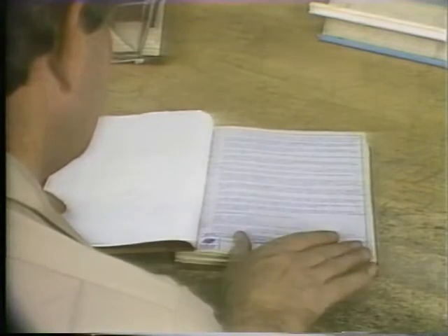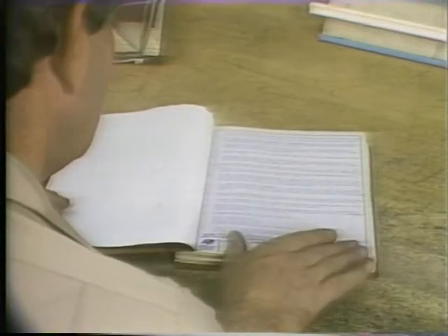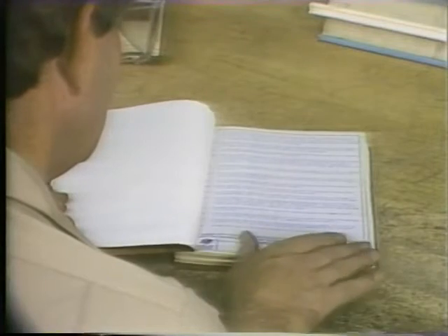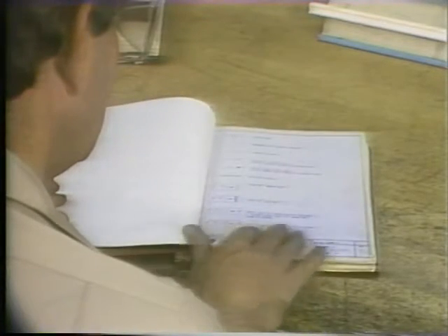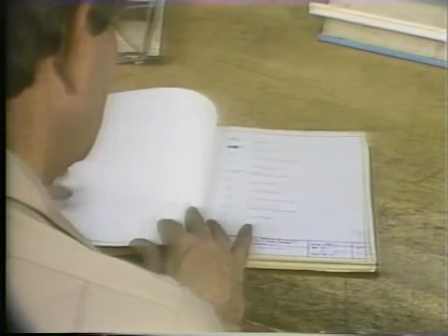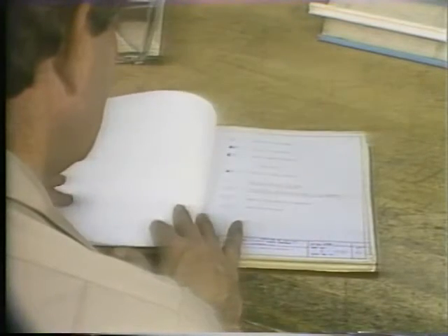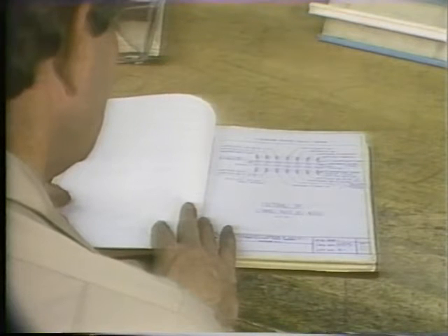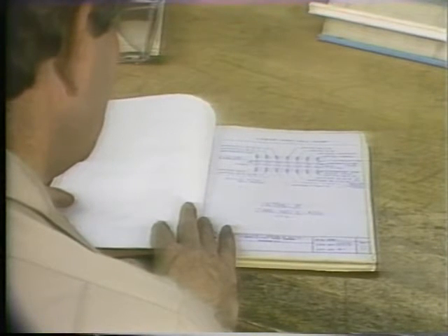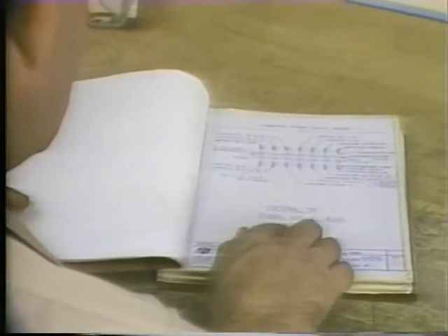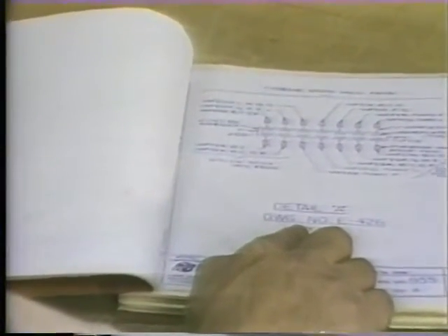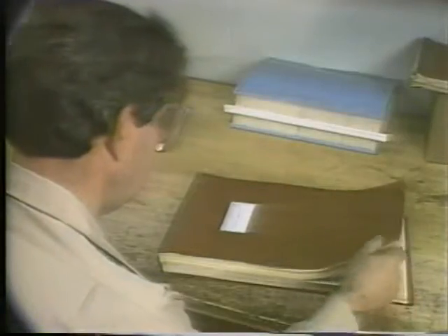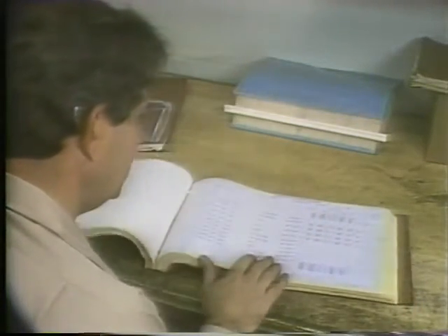The Raceway Notes, Symbols, and Detail book gives you an explanation of special or unusual symbols, and it defines the type of raceway. The notes state any special consideration taken when the raceway was built and installed. The detail section of the book contains drawings that show exactly how specific portions of the raceway are put together. It usually covers areas on the diagram that are too small or crowded on the main diagram to show detailed information. The other book we mentioned is the Raceway Schedule.